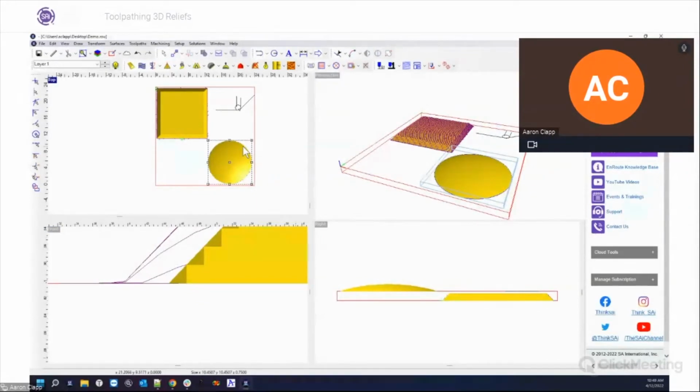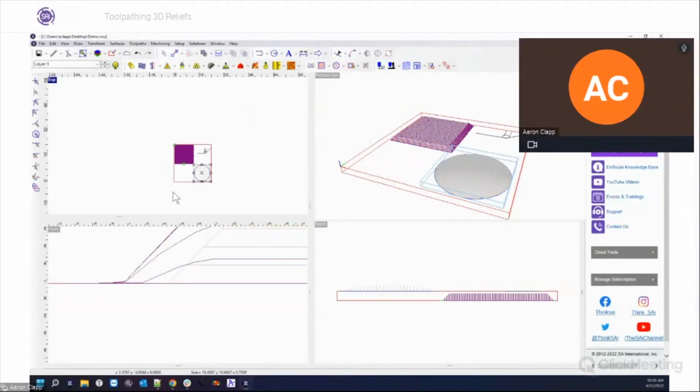That overcut value is going to be really, really important. So when we're cutting 3D objects, check the overcut. Typically, you never want to go more than half the diameter of the bit. That's just a general rule. You can, but just know that half the diameter of the bit will typically do it if you decide to go that way. So that's something to keep in mind.